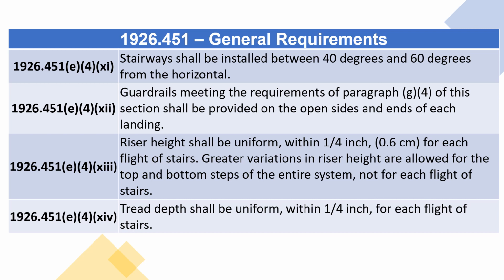Greater variations in riser height are allowed for the top and bottom steps of the entire system, not for each flight of stairs. Tread depth shall be uniform, within a quarter inch for each flight of stairs.